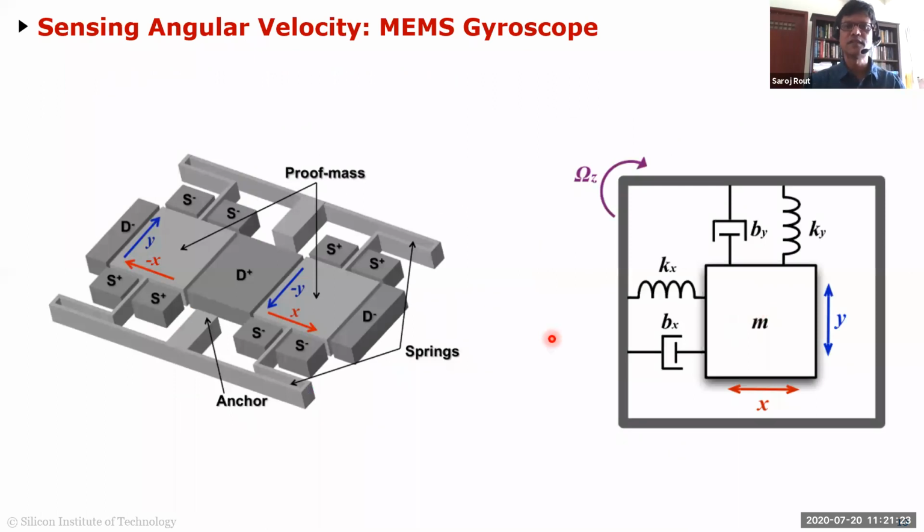Same thing, the angular velocity I was talking about. So this is one chip, a different kind of gyroscope, but a similar principle. So like I said, I've been designing circuits for sensing this angular rate for 7 years now for this company, which is Panasonic now. So the idea is to sense angular rotation. For example, you take your cell phone, and when you rotate it, that angular rotation gets converted to what's called a Coriolis force. That's the classic physics Coriolis force. And so essentially, it's a small mass system. Again, this is usually 2 millimeters by 3 millimeters or 3 millimeters by 3 millimeters, something like that, very, very small.